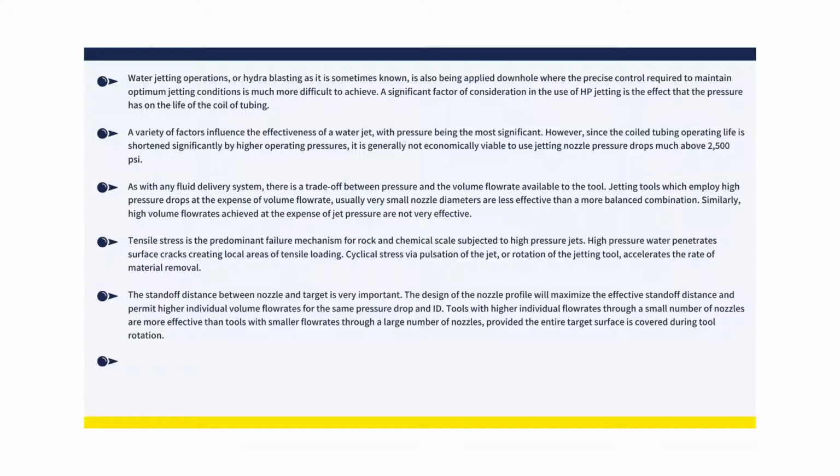The design of the nozzle profile will maximize the effective standoff distance and permit higher individual volume flow rates for the same pressure drop and ID. Tools with higher individual flow rates through a small number of nozzles are more effective than tools with smaller flow rates through a large number of nozzles, provided the entire target surface is covered during tool rotation.